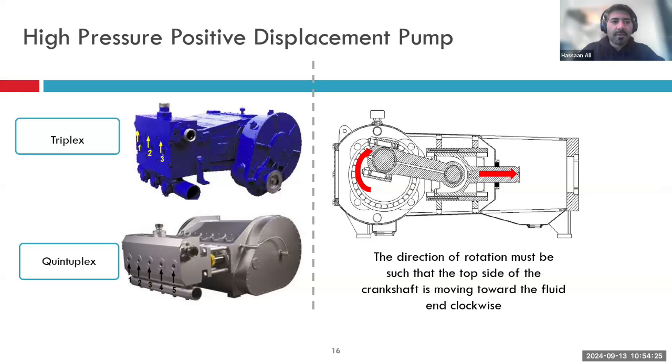A very good question, actually. It's about failure modes. I will try to address one question first. These pumps do require a lot of maintenance. Usually there will be daily checks, weekly checks, monthly checks, and then you will have service level 3 maintenance, in which the whole pump will be taken apart piece by piece. Everything will be inspected, and some of the things will be changed.